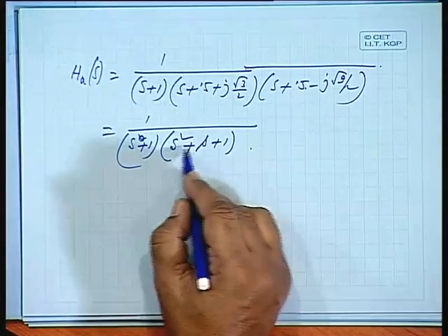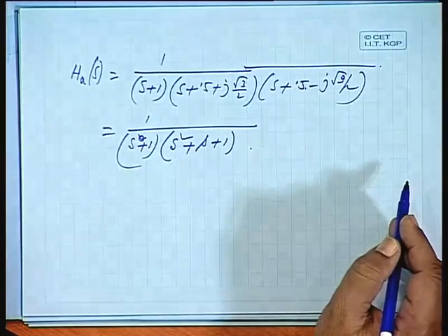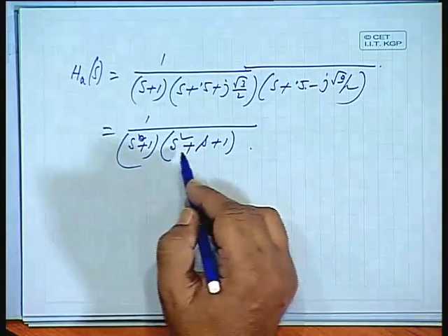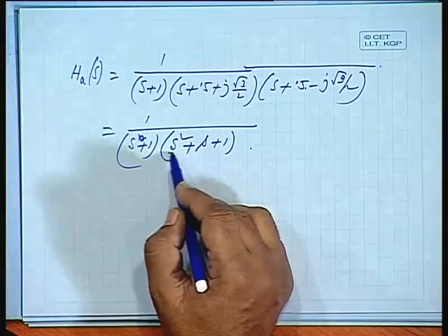There is no scope for minus signs, all right. Routh-Hurwitz criteria says a polynomial should not have any negative coefficients if it has to be stable. So, in a stable filter you will always get plus terms. So, this is my analog filter.